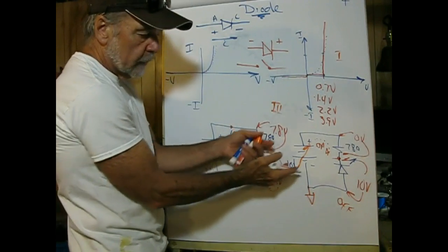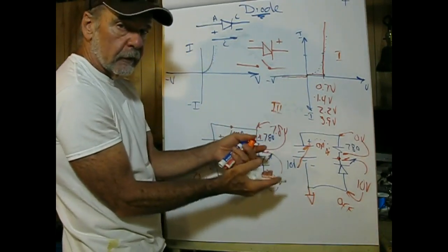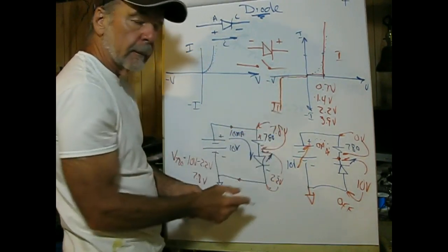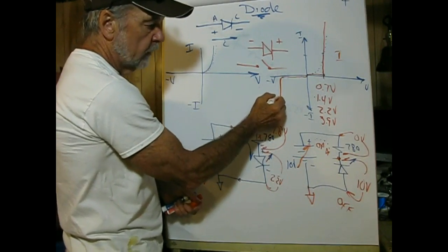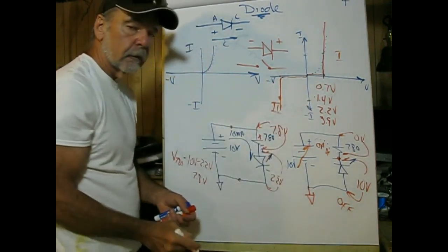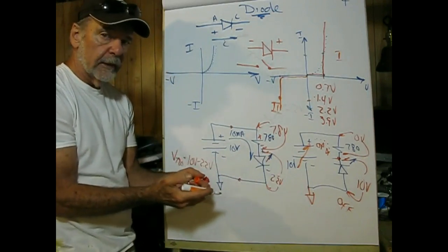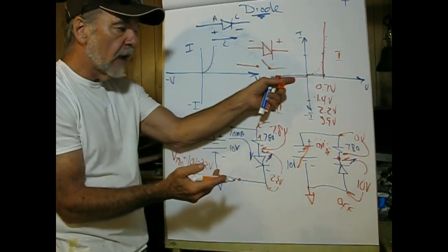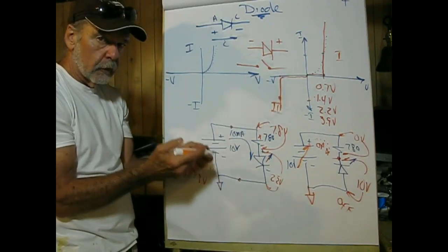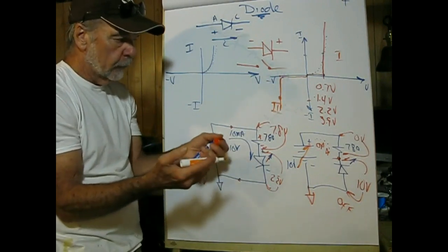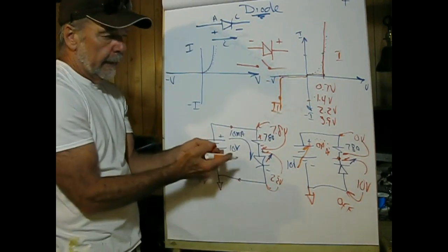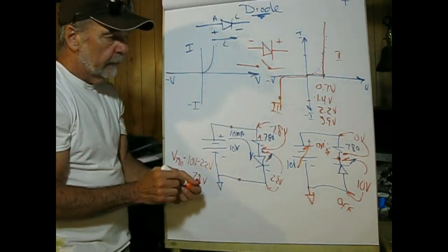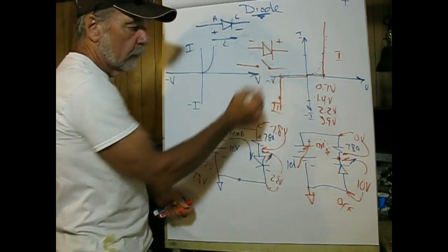Now what that means is that the potential can actually rip electrons out of orbit and cause current to flow. It'll hit a knee and the current will rise rapidly. So right here we have a significant voltage and a significant current, the product of which is a relatively high power, which can destroy the device. Now some devices are designed to operate in this region, and they're called Zener diodes, and there are some others in their family, precision diodes, and as long as they're designed within the safe area of power dissipation, they are quite capable of doing a good job of regulation.